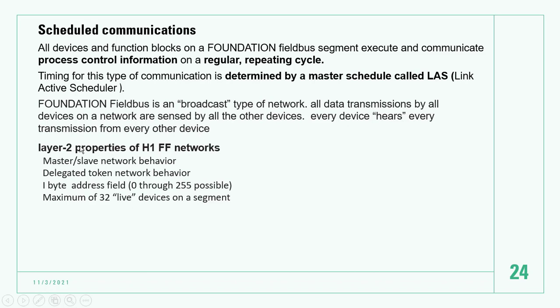So the property of the H1 FF network, the Foundation Fieldbus behavior, is master-slave network behavior. The LAS is the master and the other devices are slaves. It is a dedicated talking network behavior. So it broadcasts.